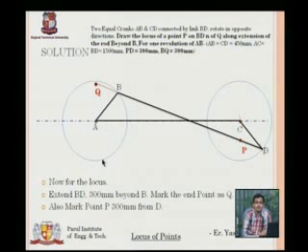So I'll have different positions of the driving crank. Now what do I need to do? I need to plot the positions of the driven crank according to the positions of my driving crank. Matlab, I have the position of AB, so I got the position of CD. Now if I have position say AB1, so I'll have the position of say CD1. This is what I need to do. How will I do it? First I'll divide this into 12 parts. Then I will take my B1, radius equal to BD, cut an arc on this particular circle wherever it is suitable. So I'll get the position of D1 according to B1.